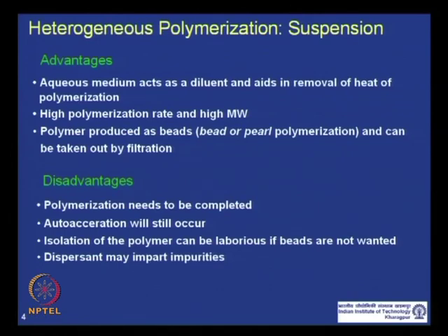Now, because you are planning to take out the polymerization at the end of the reaction in the form of beads and take it to the application, the polymerization must complete. So, you should be able to take the polymerization till the equilibrium, and complete the reaction as much as possible. Auto acceleration will also happen because it is bulk polymerization, but in this case it is not that problematic like the case of pure bulk polymerization.